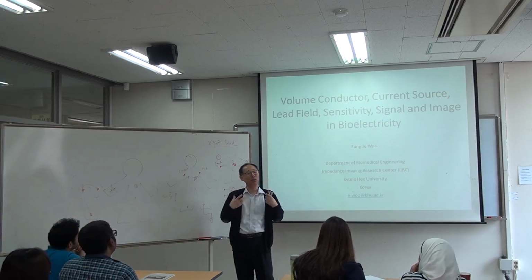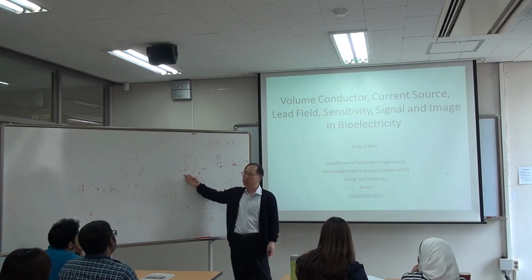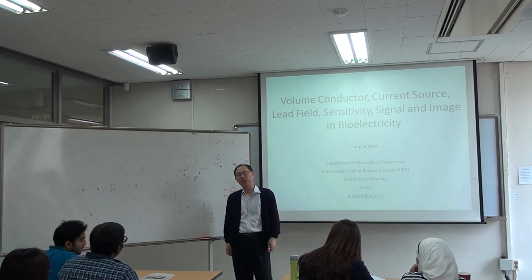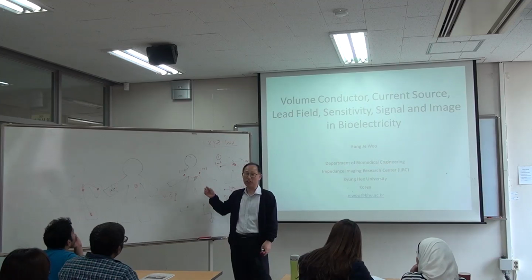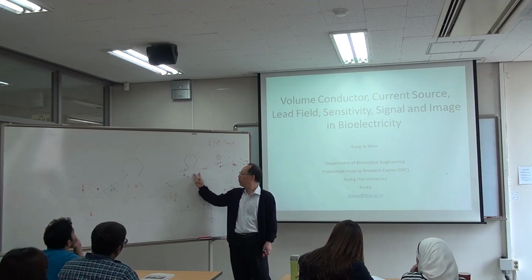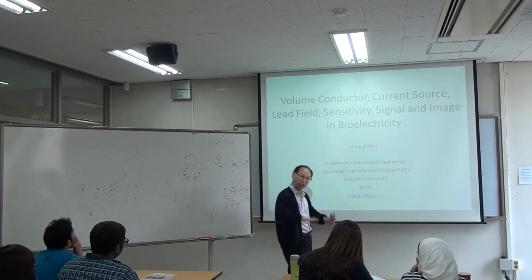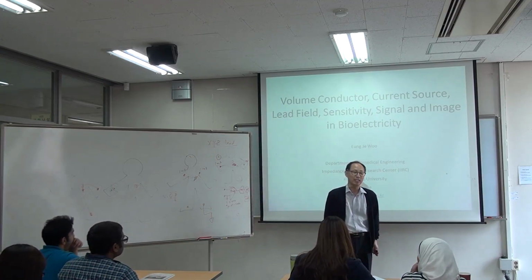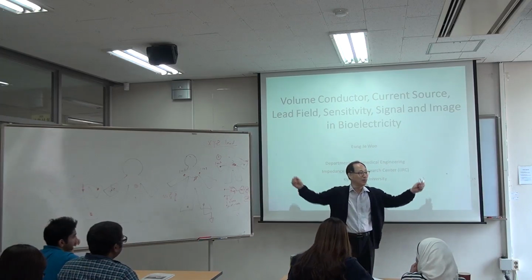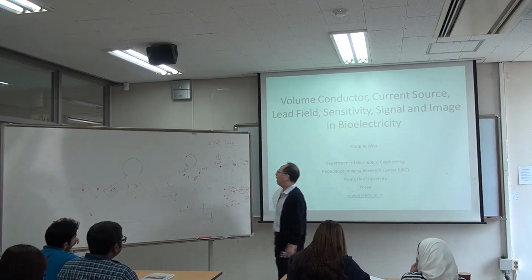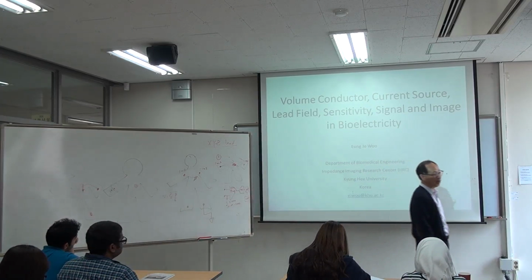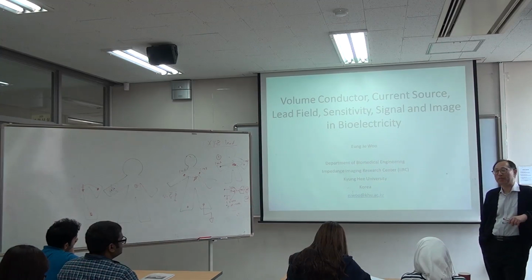So when people move, there's going to be a change in contact impedance that's going to produce motion artifact. That motion artifact has nothing to do with the ECG signal itself. So this position is better to reduce motion artifact because the trunk doesn't move much compared with the arm. But other than that, the ECG signal amplitudes are almost the same.